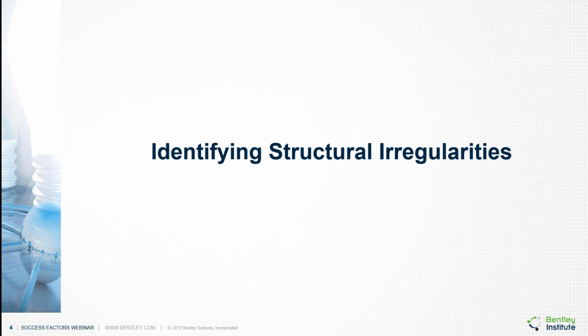As structures have gotten more complex, and as these structures have been subjected to harsh loading conditions, we're learning that certain configurations are more prone to damage and failures. To protect against this, the building codes have become increasingly more complex. Codes now explicitly recognize certain configurations, referred to as structural irregularities, or similar terminology, and include extensive requirements for determining their existence and for abating their consequences.